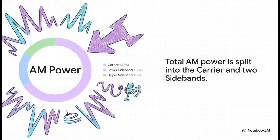Visually, that total energy is split strictly between the carrier wave and the sidebands. But here is the truly fascinating part. The carrier itself contains exactly 0 of the original message. No way, right? All of the actual information, your voice, the music, whatever it is, resides entirely within those two much smaller sidebands. The carrier is really just a high-powered vehicle doing all the heavy lifting to push those sidebands through the air.